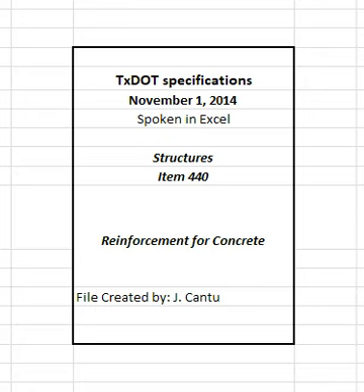ASTM A996, type A, grade 60. ASTM A996, type R, grade 60, permitted in concrete pavement only. Furnish ASTM A996, type R bars as straight bars only and do not bend them. Bend tests are not required. Or ASTM A706, grade 60 or 80. Provide the grade of reinforcing steel shown on the plans. Provide grade 60 if no grade is shown.